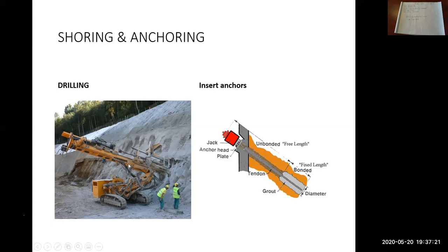I'll do a sketch here of exactly what I mean by excavation, then shotcrete, excavate, then shotcrete. This is what a typical anchor assembly looks like. Here's your shotcrete face. The anchor goes in on an angle, and your engineer would design what that angle is.